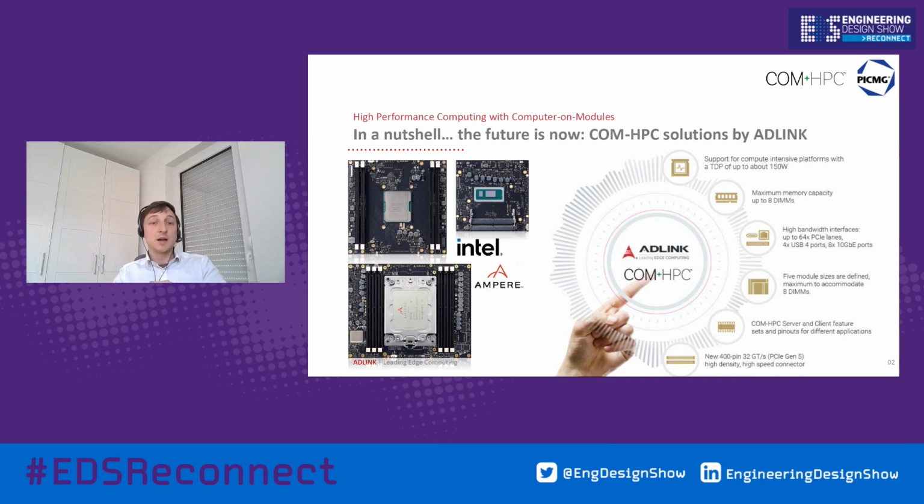COM-HPC Server and Client with its sub-feature sets are covering both markets, headless server computing and traditional display-powered solutions. And last but not least, all of these state-of-the-art interfaces become easily available through this brand new board-to-board connector, which is ready to cope with 32 gigatransfers per second on in total 2 times 400 pins on each computer on module.